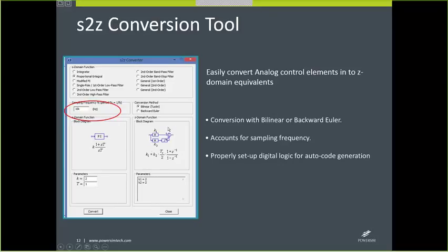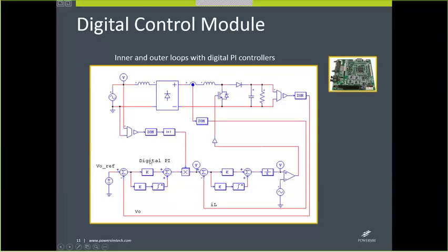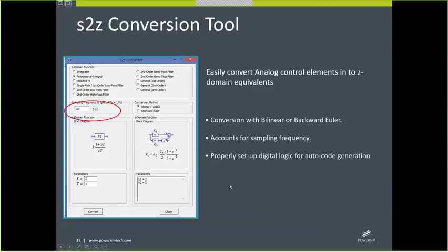As we can see here, we're doing a PI controller with Tustin, and if we go back one slide, we see that this is in fact the implementation that we needed for that digital PI. Basically, it helps you properly set up that digital logic with the correct parameters.